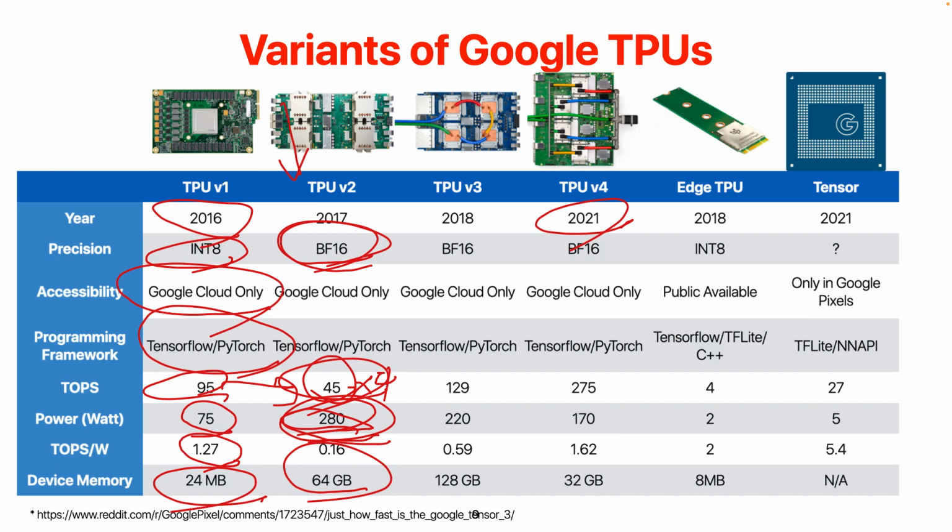So that's why in the TPU v2, you see a significant growth in memory space. And the other thing is that if you want to support these flops, you also need to make sure that your data supply is smooth enough. If you only provide just a good enough amount of data, it's not going to saturate the hardware. So what you can do is be more aggressive, and have maybe double buffering, a lot of these kinds of mechanisms available, so that you always have data that's already ready in the memory, right?